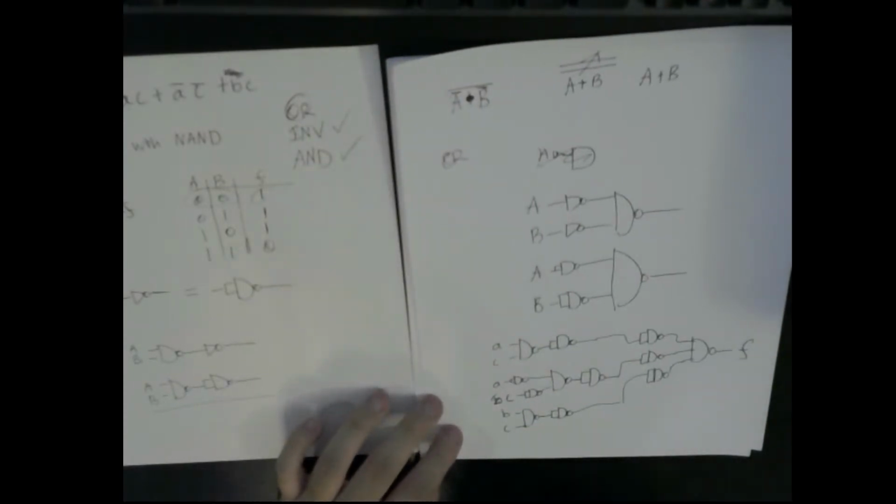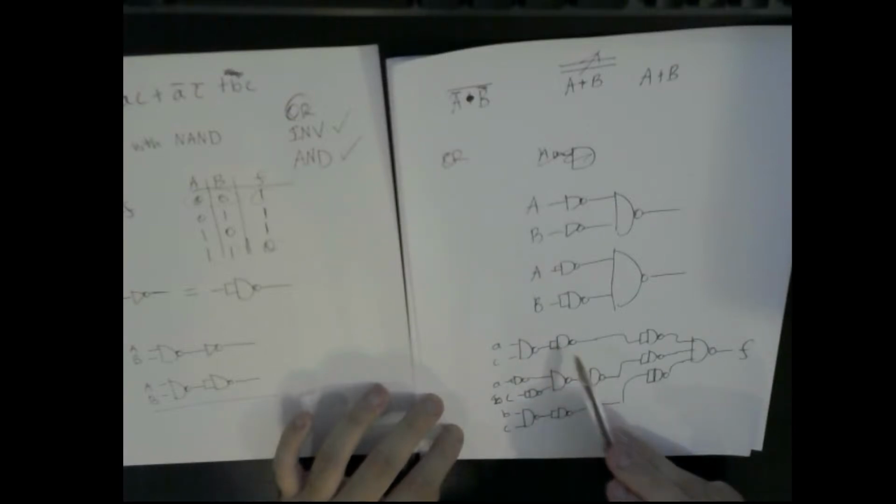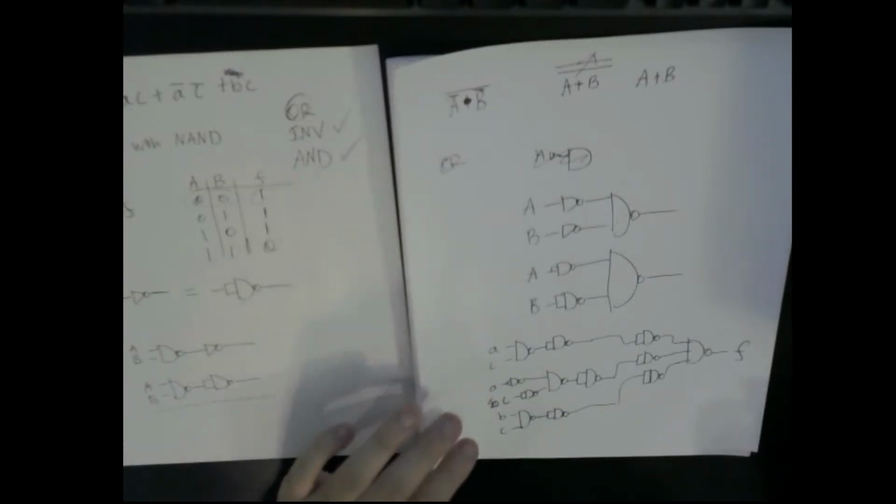So look at this. We have an AND gate right here that's acting like an AND gate, and then we have an AND gate inverter and an AND gate inverter. They're both in series with each other, and we can remember that. Yes, exactly what someone just said in chat. We can cancel these inverters, because two inverters together is that double negation Boolean algebra law.